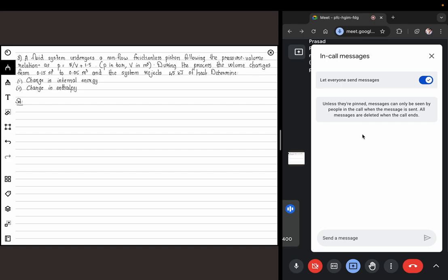So how do I calculate change in internal energy? All of these problems are based on the first law. If you have one unknown, you can get only one equation, and the one equation you are going to use here is the first law. So the net heat transfer is given by work done plus change in internal energy. I'm just avoiding the delta before Q and W for clarity. Q is already provided as 45 kilojoules, and it is heat rejected from the system, so Q is negative.